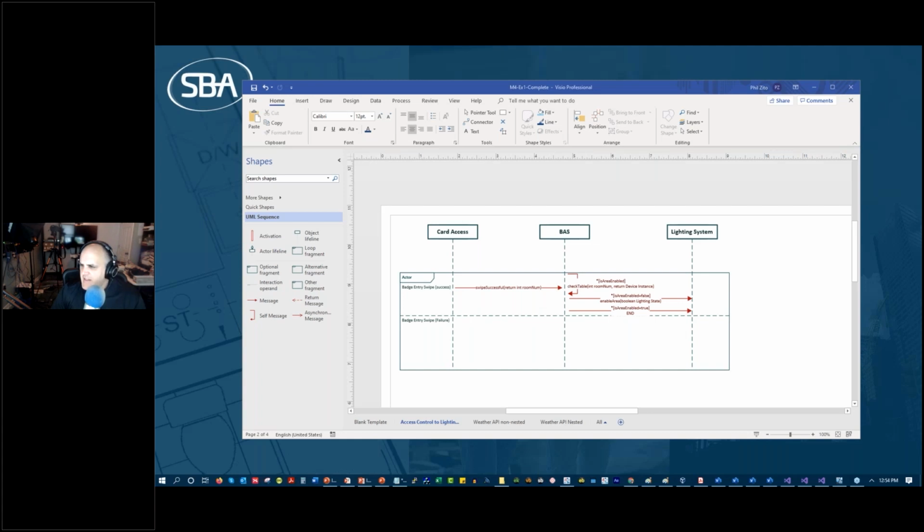Can I explain system integration with BTU metering systems? In my experience, the majority of BTU metering systems have been either a physical interface via a 2-wire pulse, and based on the pulse, that would equate to things, or Modbus with a bunch of registers, or BACnet. When you do that, you just simply grab the data type, understand it, and then map in the appropriate points based on what your use case is.